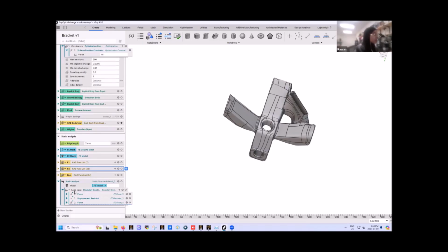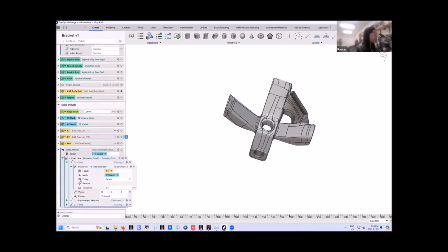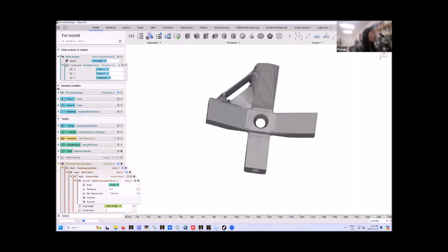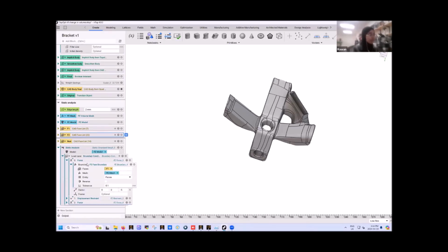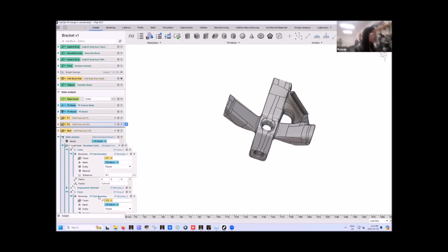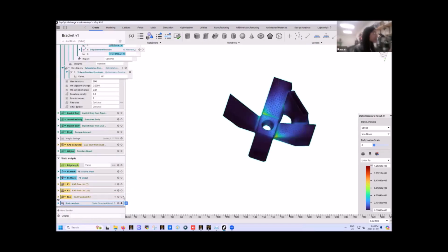So inside the static analysis, you'll have to insert, again, the model, the FE model, as requested, and the load conditions. What I did here is I already created the blocks inside the static analysis block, unlike what we did in the original design, where you can see that we created the boundary conditions, the forces and the restraints outside as a separate block, and then we started importing them into the input. However, in here, I created them directly inside the static analysis block. The force, I give the same values, -5 and -2. And let's run the static analysis and see.